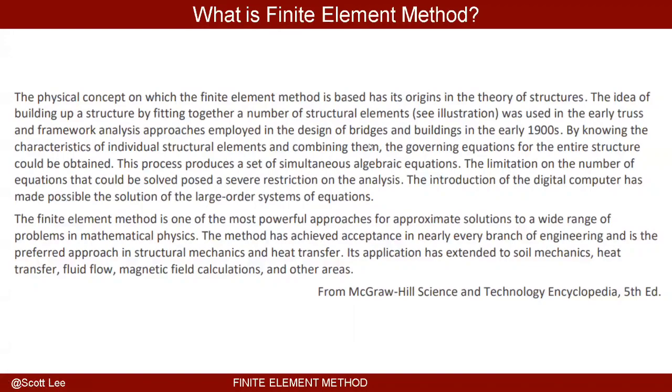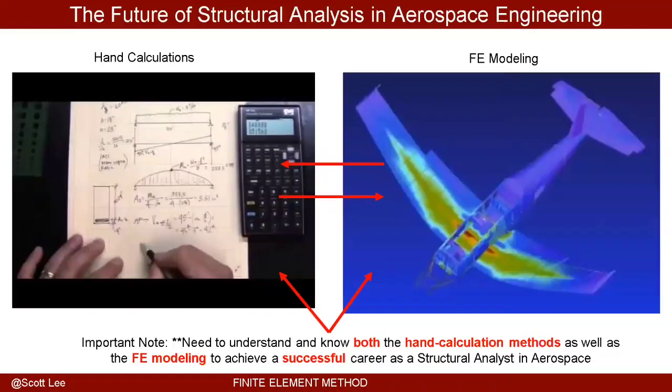And typically in the finite element world for structural mechanics, the thing that you're solving for is your displacements. We call it the displacement method. And essentially, you solve for the displacements using a solver called Nastran or Abaqus, and from displacements, you can calculate your strains, stresses, and your forces. That's a very high-level overview.